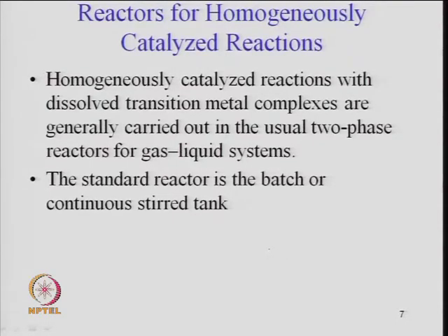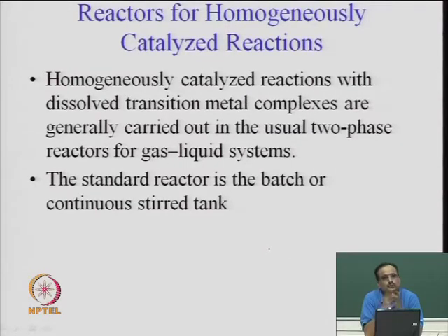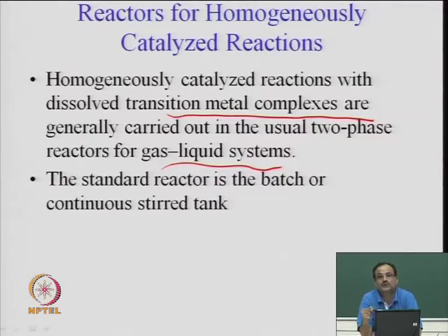So, the idea of nanoparticles, or when we look at a better dispersion of a metal during the catalytic reaction. There, during the homogeneous reaction, we do not have any mass transfer limitation or diffusion limitation into the pore of a catalyst, which is the problem in the case of heterogeneous catalyst. These transition metal complexes are in the liquid phase, and generally in two-phase reaction systems, gas-liquid or liquid-liquid. So, they act as a homogeneous catalyst.